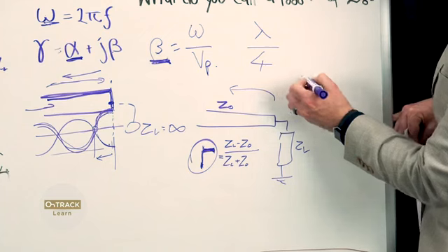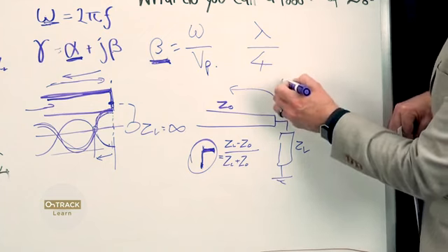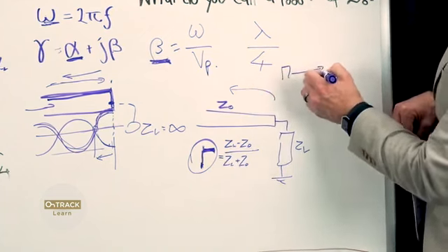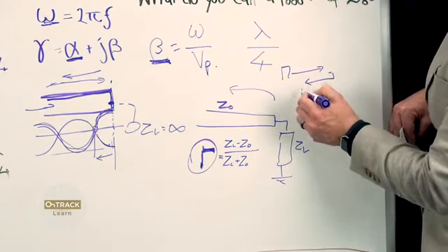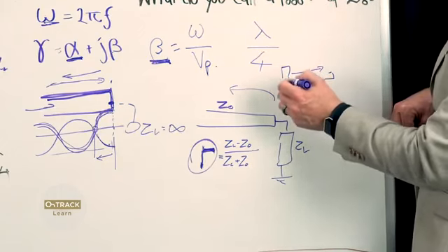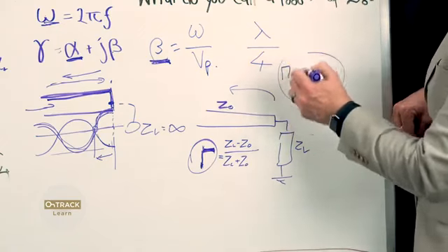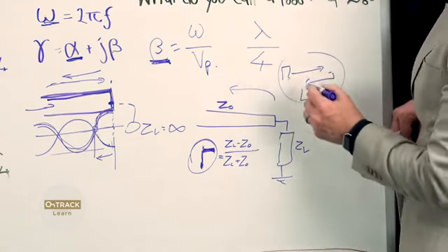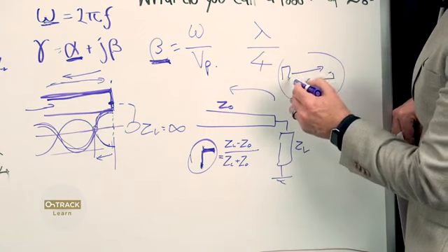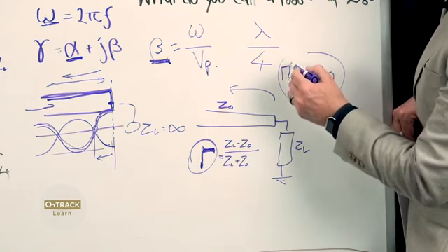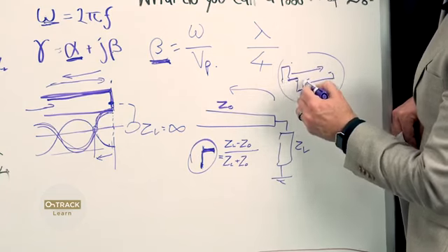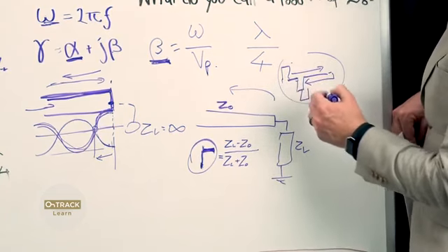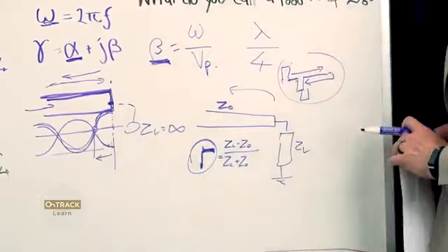When you put a pulse down a shorted line, the pulse travels down the line, and when it reflects, it comes back negative. You can see that on the display of the TDR, and see how long that line is based on the time interval between the positive going pulse and the negative going pulse where you're measuring it.